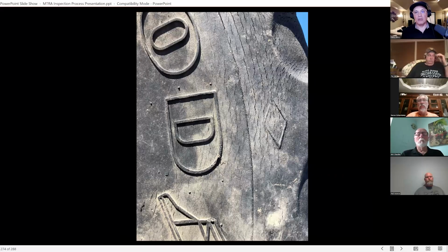it's at least to minimize, to the best of our ability at this point, this issue. Because what happens when you have tires that get dry rot like this is that moisture works its way down through the rubber. In other words, it's not always that the sidewall is going to blow out.